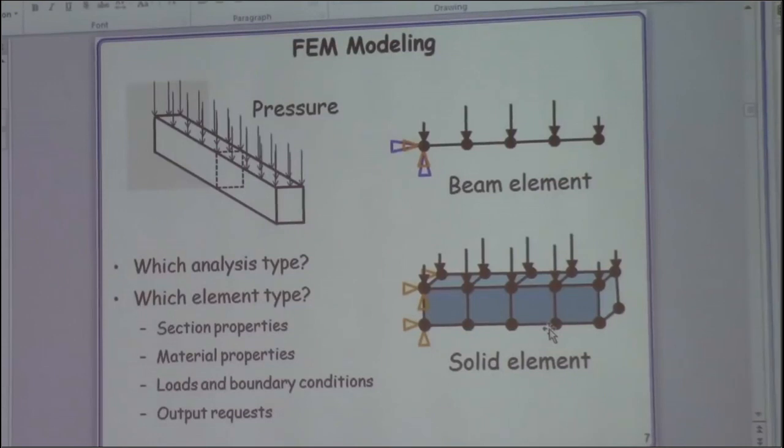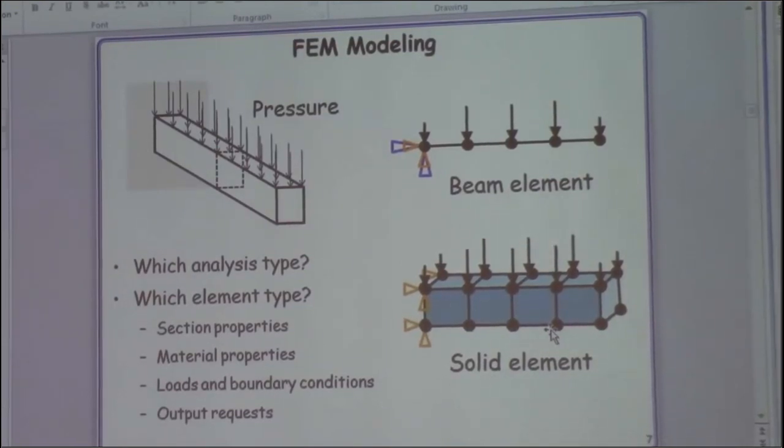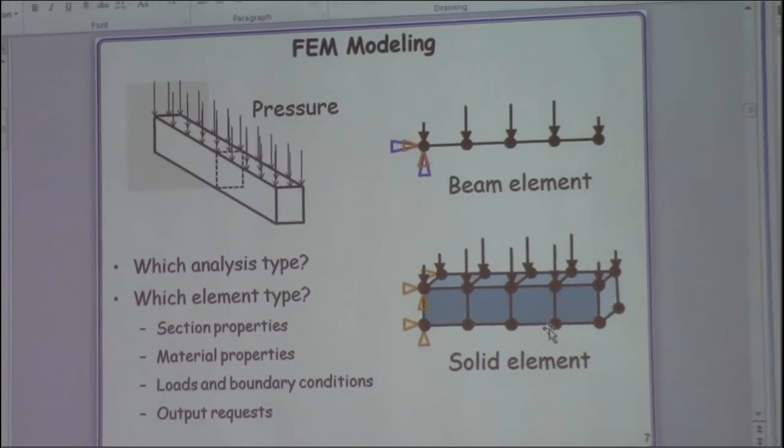Yeah, I was just going to ask, is the pressure applied at each node? Because it's like a point, not an area, so how is that defined? Yeah, you will learn that in your later FEA class. For an FEA problem, you cannot just apply pressure everywhere. All the force, pressure or concentrated force, you need to discretize at each node. Force can only be applied at nodes.